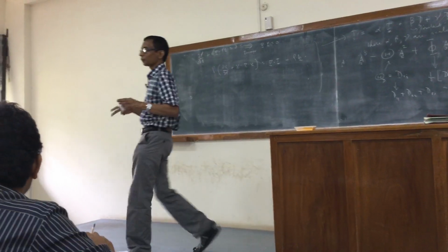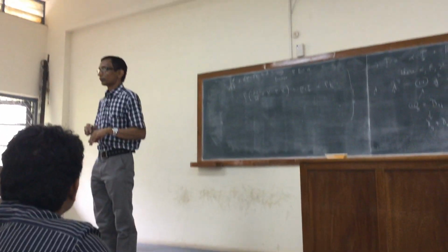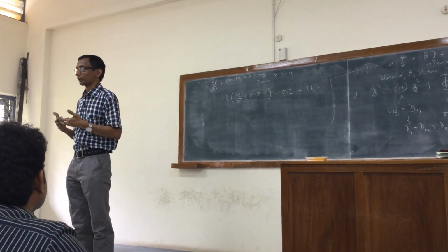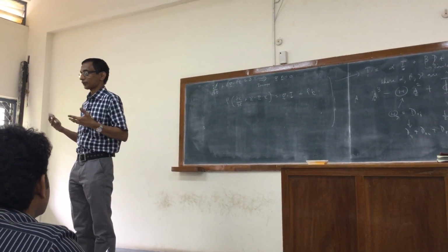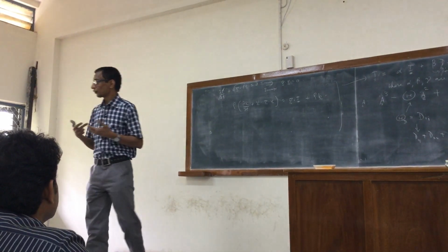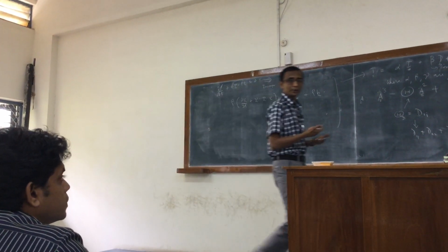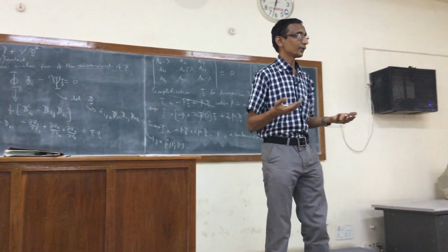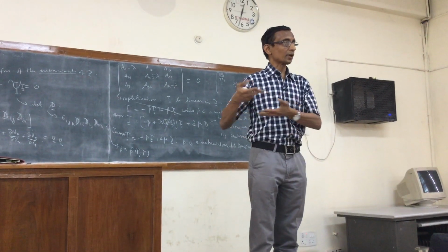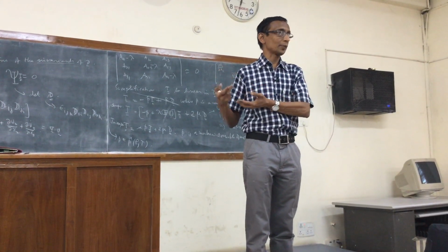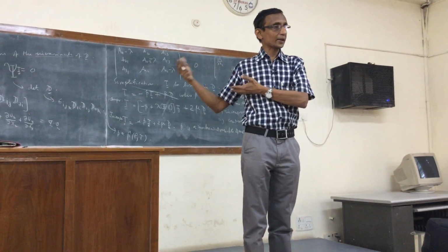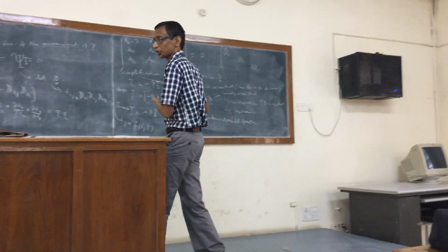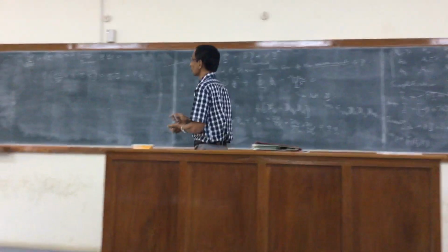But in terms of the incompressible fluid, because in effect the volume doesn't change, or the specific volume doesn't change, there is no effect of the pressure on the density because it doesn't change. So the question of an equation of state doesn't arise. So the pressure is not a thermodynamic variable to be determined by the equation of state, but a mechanical variable to be determined by solving the equation of motion along with the equation of continuity.